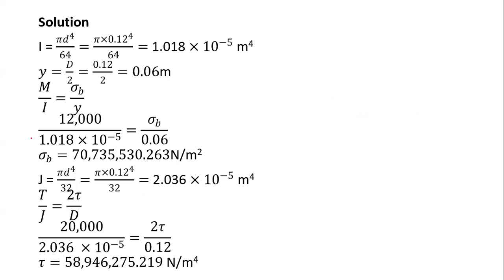Now, looking back, you will notice, first of all, I need I, because in the equation that we need stress 1 and stress 3. We do not have those. To get them, we need to plug them into an equation that should have the bending stress as well as the shear stress. So if I start with figuring out the bending stress, I'll need to go to the bending equation, which is M over I is equal to stress over Y is equal to E over R.